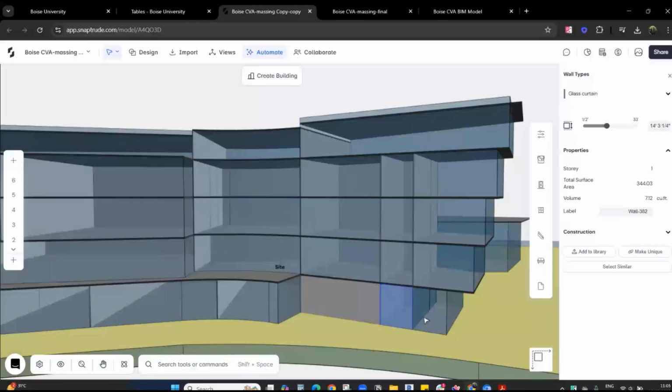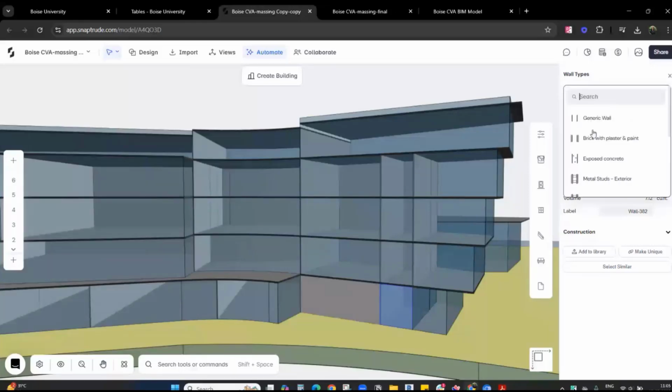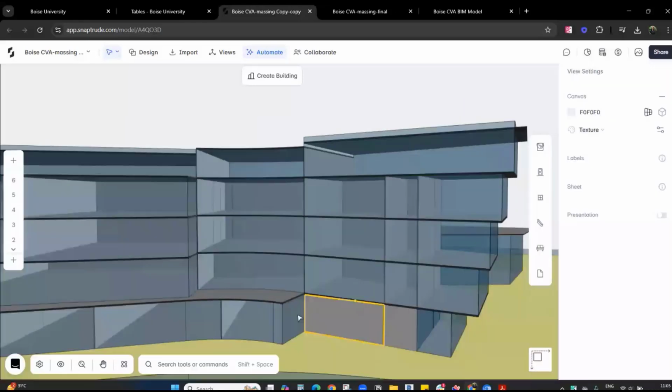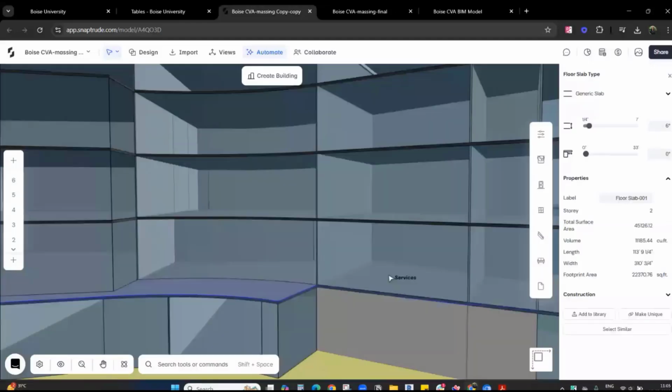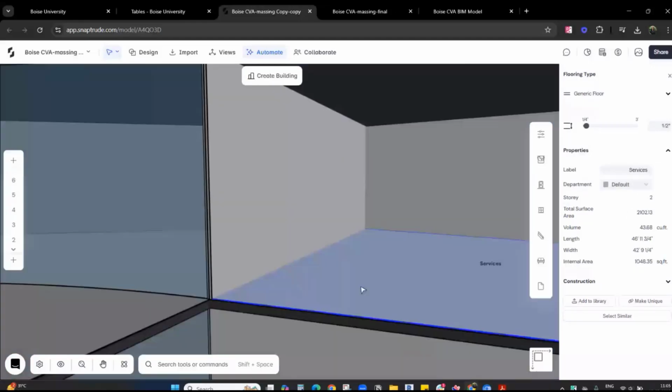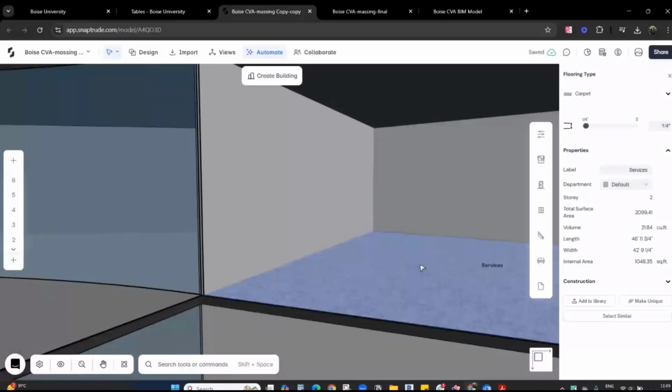All right, moving on. As I was saying, the wall types that you can see here, you can change them as you require. I'm just showing a few examples of doing this. Similarly, your floor type, the floor slab type, can also be changed. Your floor and your slab come as separate components. All of these edits you can do here. You can change it to whatever other components or types you like from the drop down here.